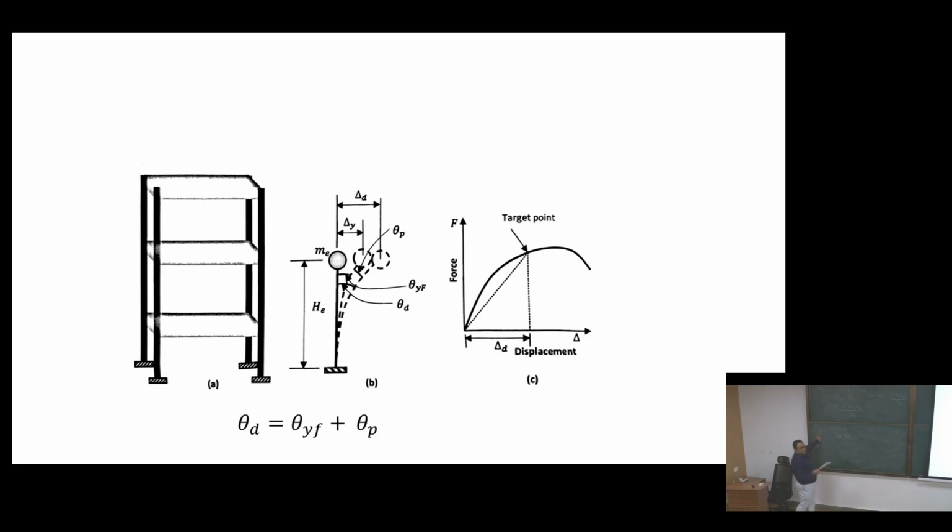Yes, but we are trying to find the cross-sectional area, right? Is there something in the definition of performance-based design that can lead you to this? So again, this document comes in handy, it's free to download, FEMA 356. That has some guidelines about deformation. And it states that for immediate occupancy, remember, this is your design drift, but this is your member deformation target at performance level, right?